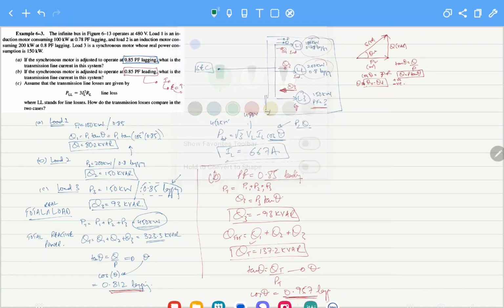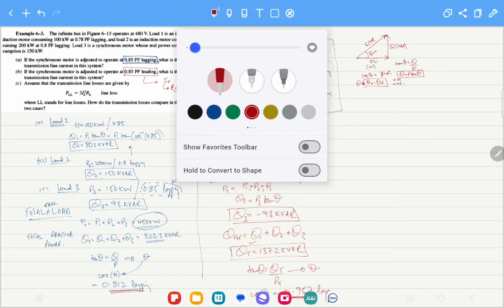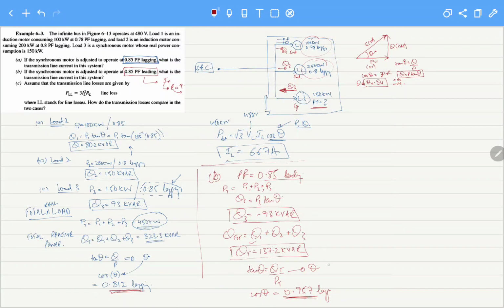And the last part shows the main advantage of all this activity. One thing has remained. We have to calculate the line current for our new power factor. We calculate it in a similar way. Now the power factor has changed and the value of IL will be, if we calculate, 566 amperes. In the same way we have calculated, only this cos θ has changed.